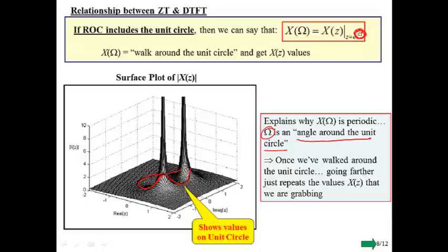So basically, we're taking that periodic DTFT and folding it on itself so all the replicas line up when rolled into a circle, and then plunking this thing down onto the Z plane right on top of the unit circle. And then the Z transform just provides some additional values off from the unit circle, some of which will be useful to us, some of which will not.